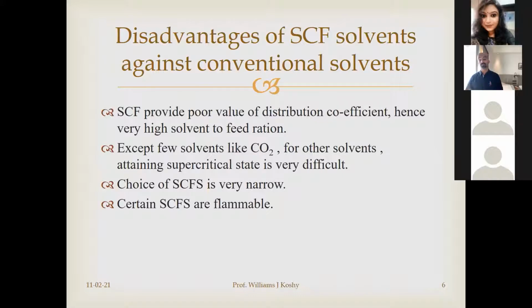But जब हम लोग बात करते हैं supercritical fluid solvents की, why it is very important to mention that these are flammable is because the temperature and pressure conditions are very harsh. अब बात कर रहे हैं 100, 200, 300, 400 डिग्री सेल्सियस टेम्परेचर की. अब बात कर रहे हैं might be 50, 60, 70, 100 बार प्रेशर की. At this extremely high temperature and pressure, you cannot afford to make slightest of the mistake, because it can lead to very big catastrophic situation.